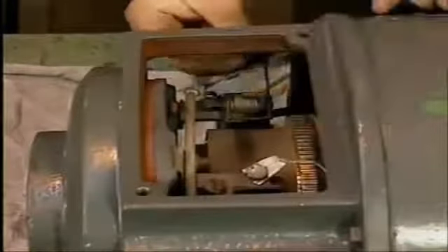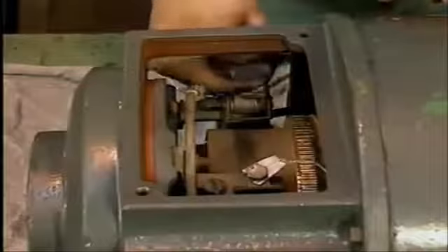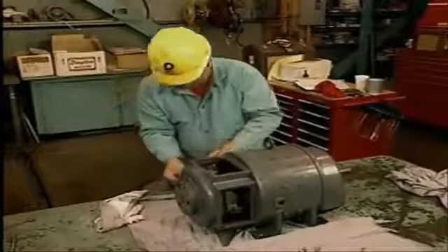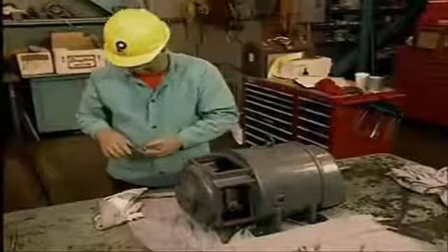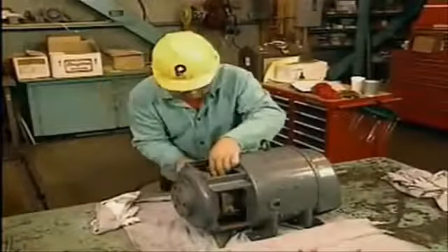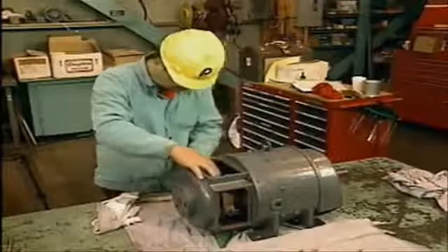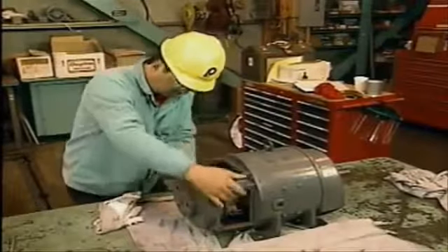The brush is then removed and inspected to see if it has the same shape as the surface of the commutator. If it doesn't, the procedure with the flint paper is repeated. When the shape of all of the brushes conform to the shape of the commutator, the seating procedure is complete. All traces of carbon dust must then be removed from the motor. The next step is to install the brushes. After they're placed in the brush holders, the brushes are moved up and down to make sure that they can move easily. The next step, if necessary, is to set the amount of tension applied by the brush tensioning devices. The tensioning devices in this example are set by the factory and are not adjusted.